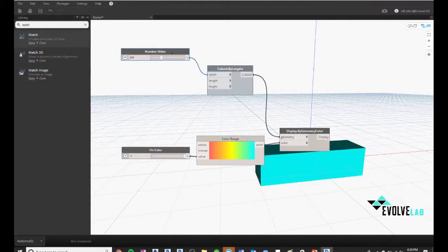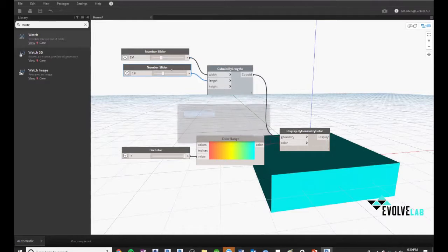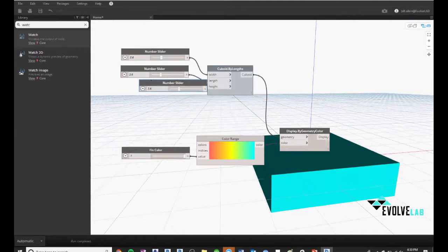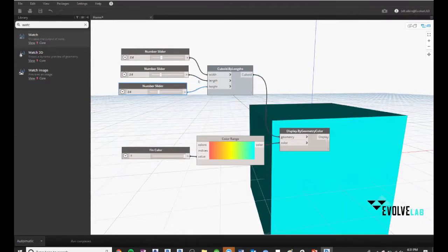And then the big piece that is really, really important, that I totally screwed up at the very beginning when I first started using this process, is that in Dynamo we often are using just our sliders and we're like, yep, looks good. But it's really important to have your min and your max set. If you have a minimum at 0, Fractal crosses it out and says, hey, that's not a good option because there's no geometry there. So something to really keep in mind is your min and max on your slider bars. Make sure that those are really dialed in.